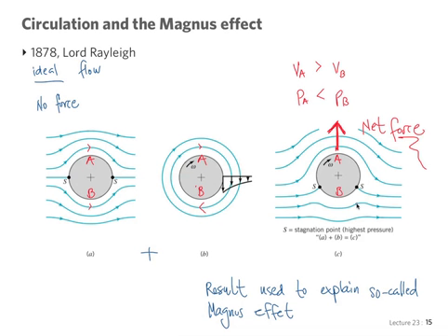The effect of the spin, because of course in the case of, say, the baseball, there's a roughness, right? There's roughness because of the seams. That roughness causes the air around the ball to be more easily dragged with it. So when the ball spins, the air spins with it, and so there's a circulation on the air added to the translation velocity, which produces this effect.